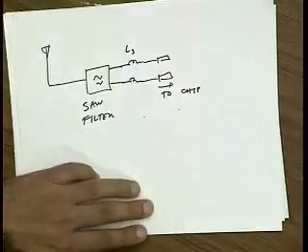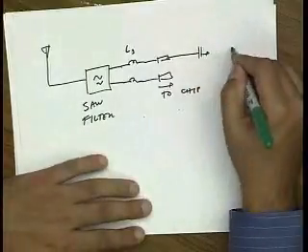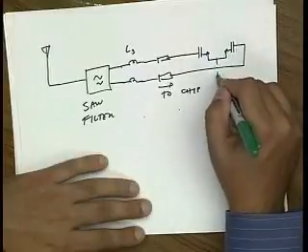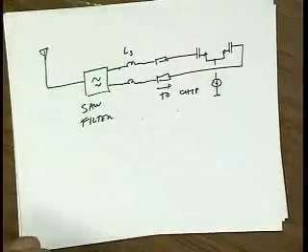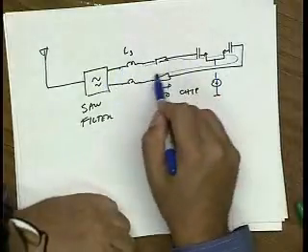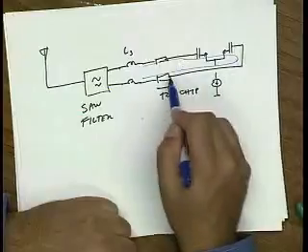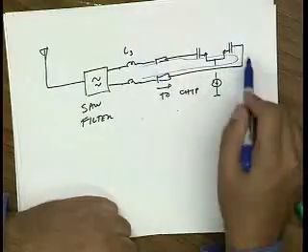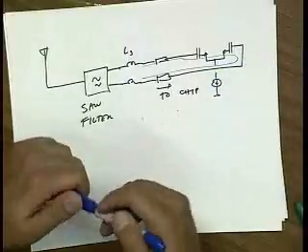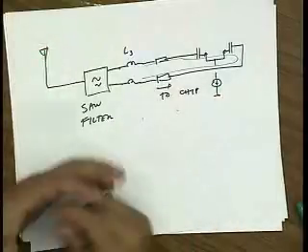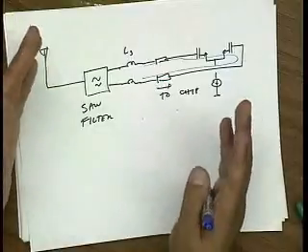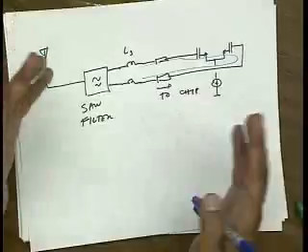And the beauty is that now the path is very well controlled. And let me explain why. So this is the path that you care about. All the current basically will flow in this loop and come out. And you can have very fine control, basically you can, with layout, where this current goes. On the other hand, ground is a little bit scary because lots of things are grounded, right? All the transistors, their bodies may be grounded. You might have multiple ground pins on a package. So if you're not careful, your ground current may take a path that's very different than you intended.